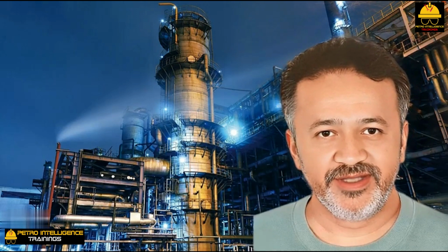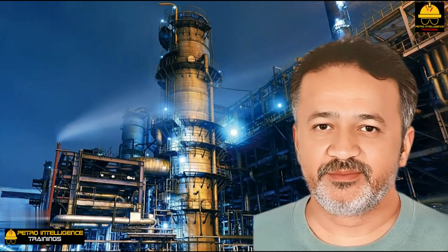In refinery steam condensation services, in both reboilers and steam turbines exhausting to vacuum surface condensers, I have observed that small amounts of non-condensables greatly reduce the apparent heat transfer coefficient. In reboilers, propane or butane may leak into the lower pressure steam side of the reboiler. In surface condensers, air could be drawn into the condenser's shell, which operates under vacuum conditions. In the latter case, I've observed that the heat transfer coefficient, which should be 200 BTU per square foot per degree F, is only about